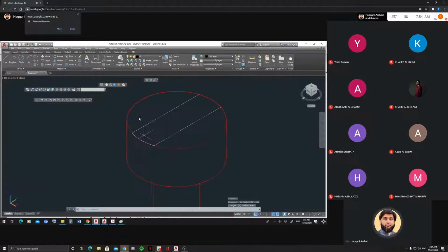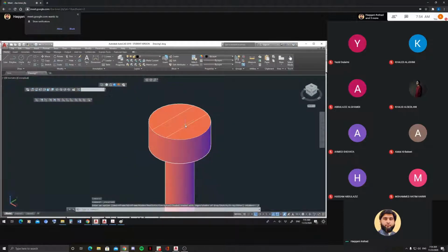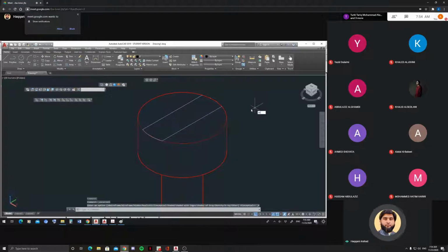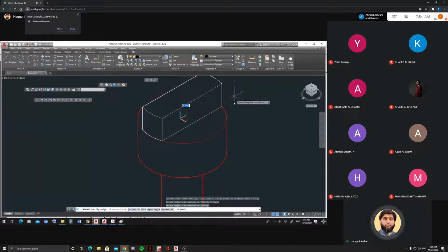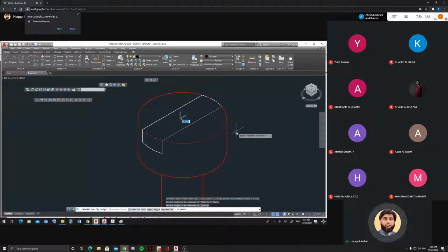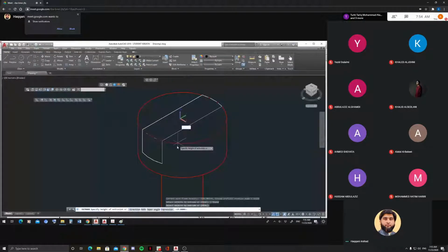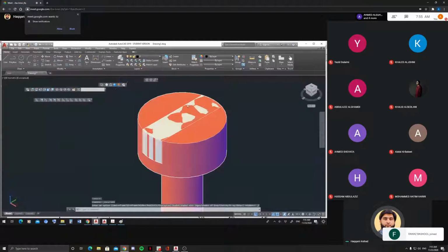Alright. Now if you see this one, I can extrude this area. Go for extrude only this area. Enter. See, it should be going down, right, to cut. So what is the height given? It is given 10 again. If you see the figure, this height is yes 10. So you go here, just put like this and just type 10. Okay. Now you can easily cut.